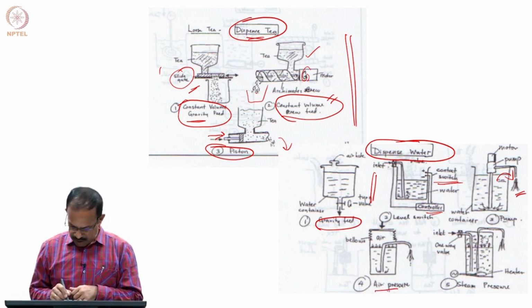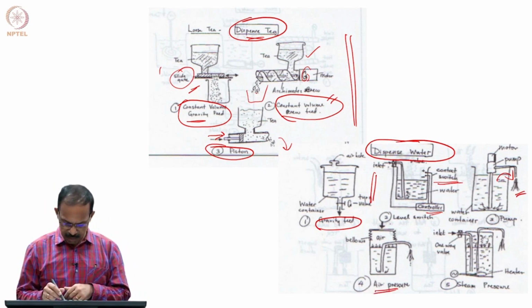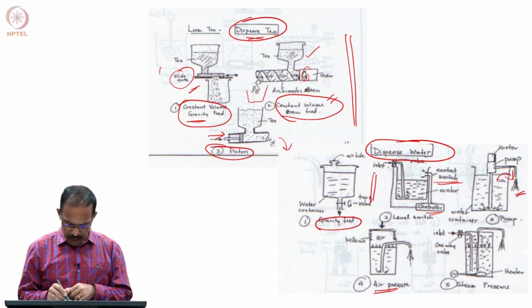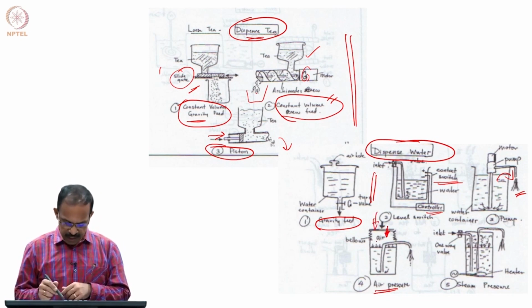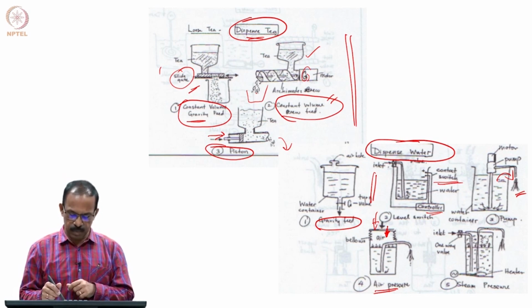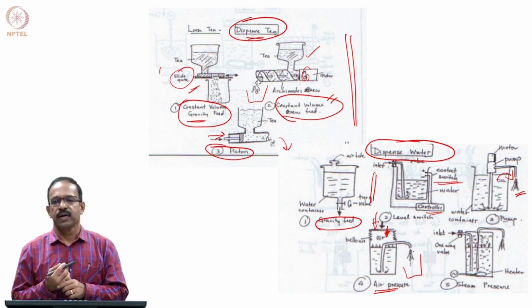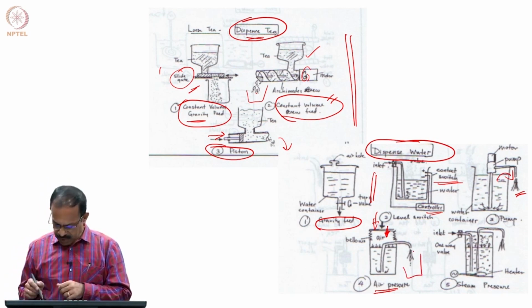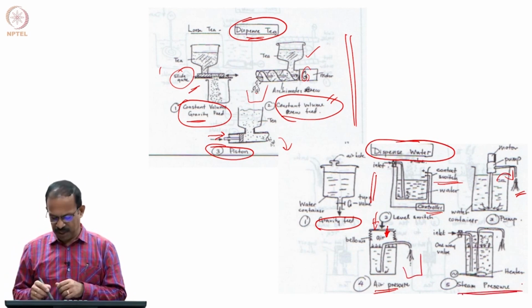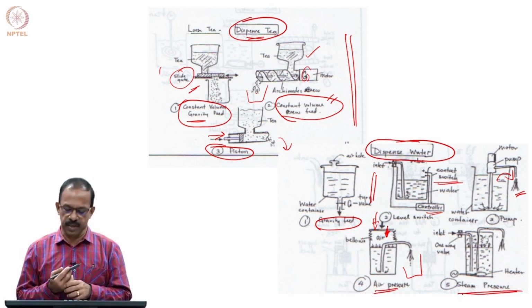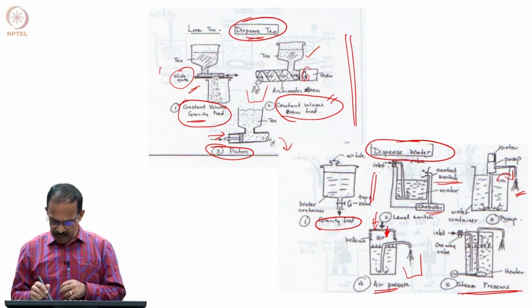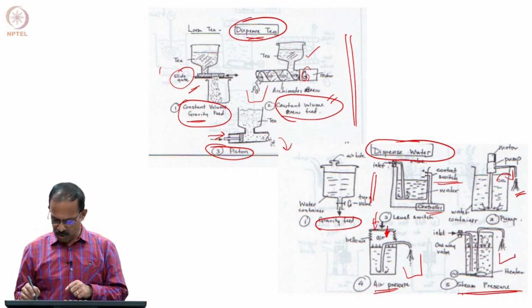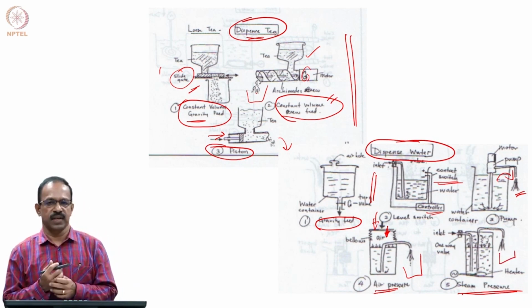Another one is an air pressure type. So, you can actually have air pressure. This is a bellows. You apply some force here to move the bellows, then you will get the pressure, the air will be pressurized, and that will pump the water out. So, that is another method. And another one is steam pressure. Instead of having a manual pressure application, you can apply steam, and that will pressurize the water inside, and then the water will come out. That is another way of looking at it.